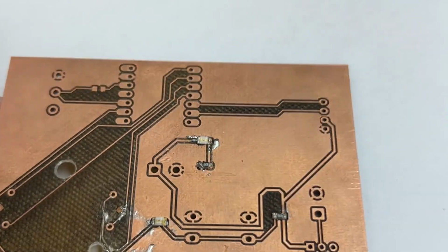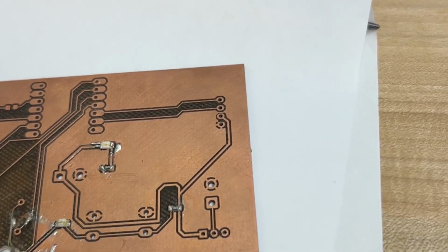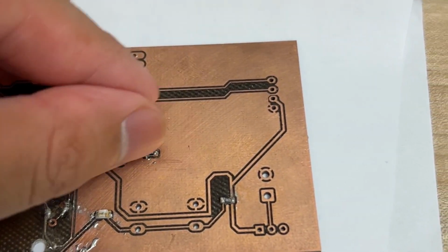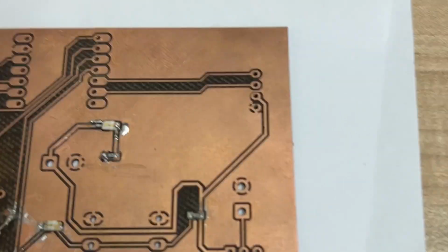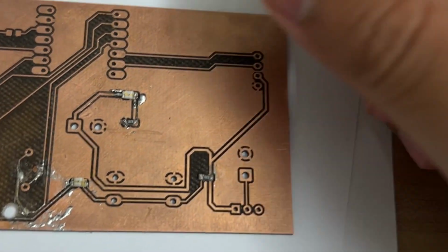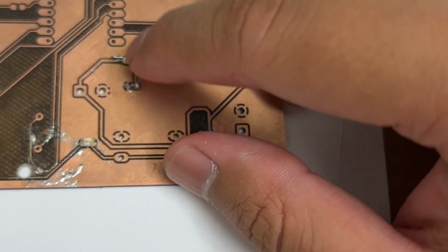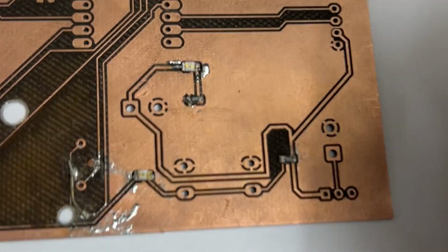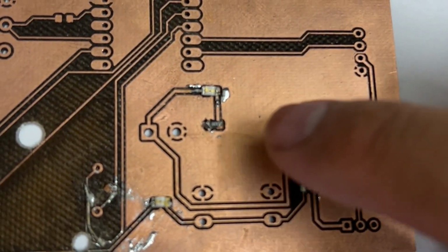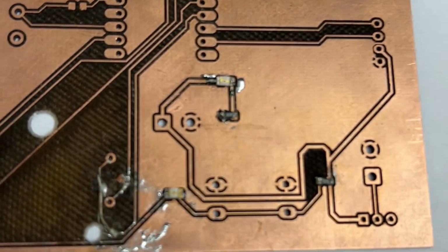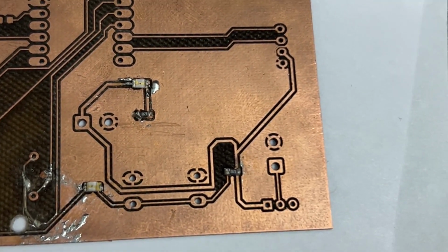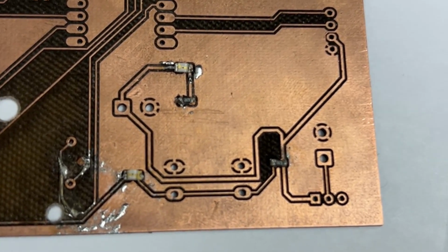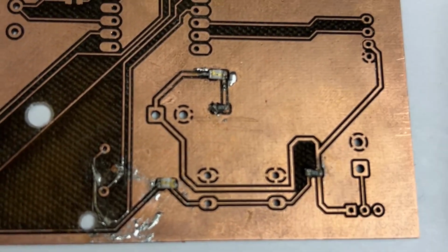because when you need to solder it, you need to have a tweezer here, right? Put the device on it, but your right hand needs to use the soldering iron to heat up the solder beneath it. And since these pads are super small and these tracks here are pretty thin, it is super difficult for you to accurately put those solders on the pads without touching all the ground planes and anything else.